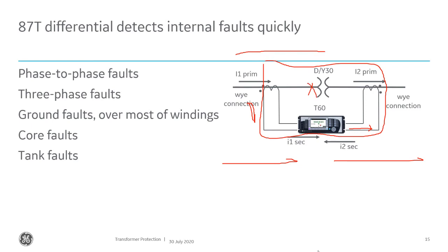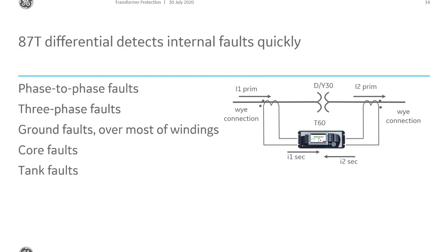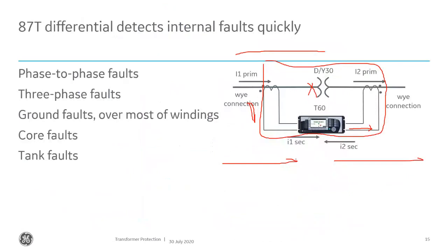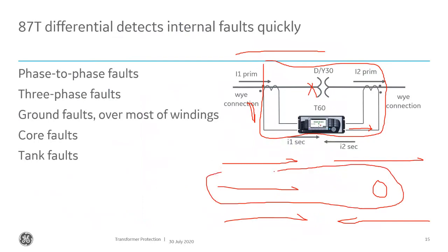Sorry, I hit my mouse wrong. So if I actually have a fault inside the transformer differential zone, one of two things happen. Either I have fault current flowing here with 0 fault current there, or I've got fault current flowing in here and fault current flowing in here. So this scenario, that looks something like 1 per unit at 0 degrees plus 0, and that's a differential that would cause it to operate.